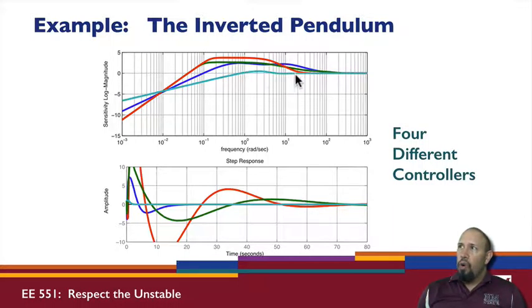And so you can see the sensitivity function here is the kind of thing that we really want. It's very low over here, and a very small area here, and yet a large value underneath here. So it does very well in terms of the overall response of the system. It's a different type of controller design. Part of the sensitivity issue is associated with the fact that we have a controller that has the dual problems of making the system stable and providing tracking.